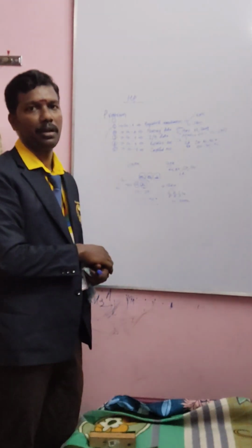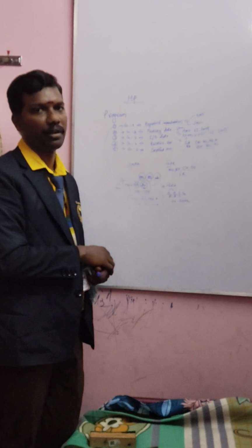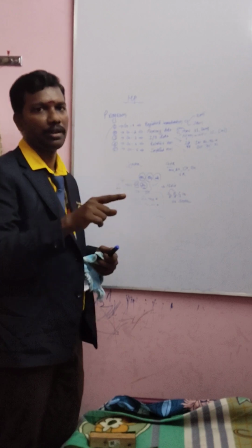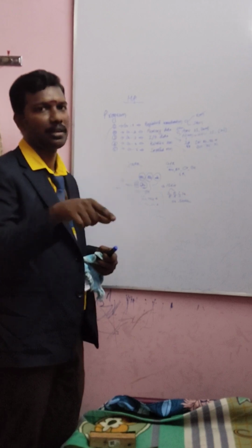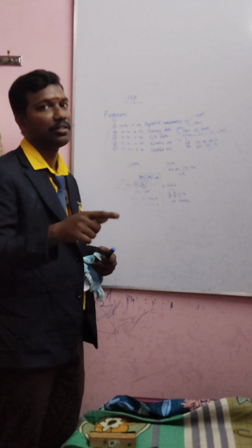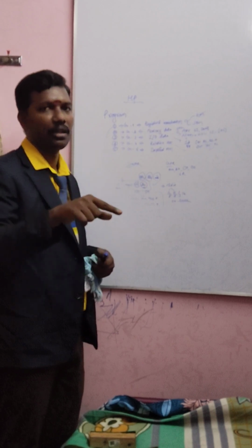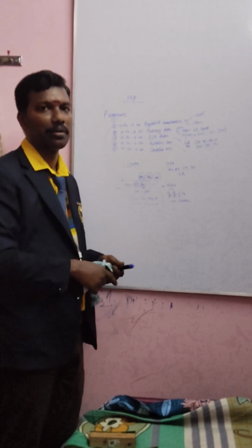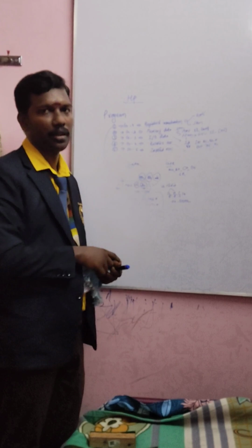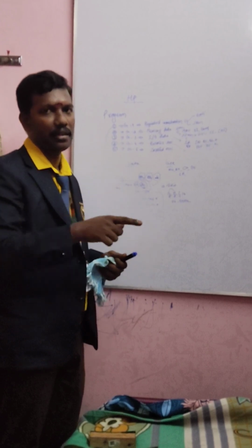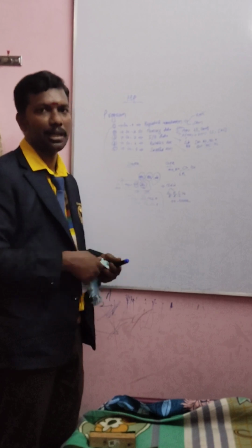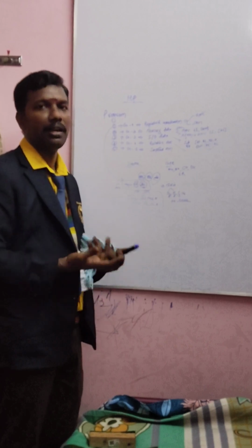So for example, MOV SI, 1500. This is a direct addressing mode. MOV SI, 1500. Instead of 1500, I just write AX or BX. So that is register indirect. Along with AX or BX plus some index register, it will be represented as indexed relative type, or JC, JNC, JZ, JNZ, JB, JNB, many things.